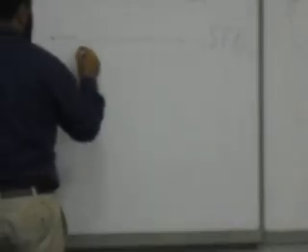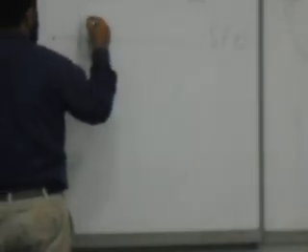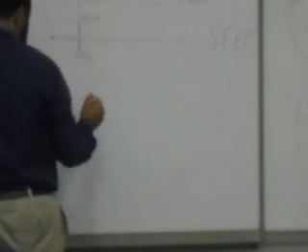Then, if I take a section just after B, this negative 2.25 will receive the 16. So what's the ordinate here? The value here will be 16 minus 2.25. Do you agree? After B, it received the 16K up. So 16 minus 2.25 is 13.75K. Here I'm having a jump. I know the shape here. This is 13.75.